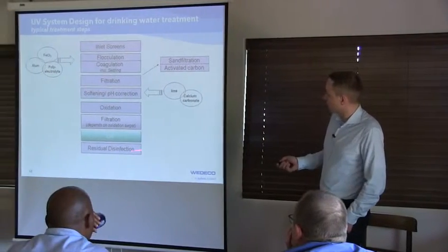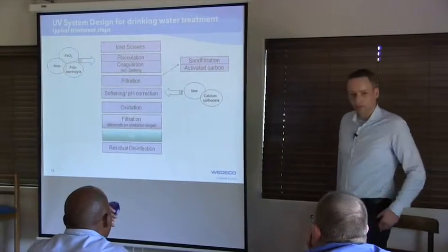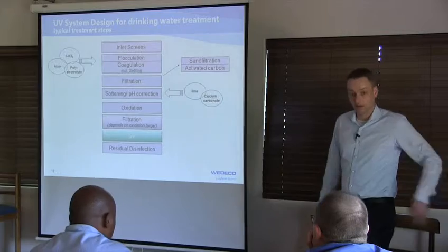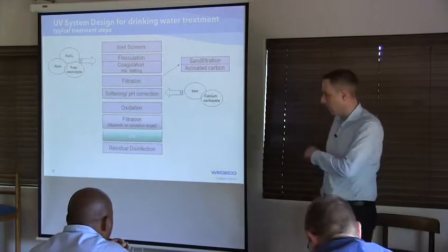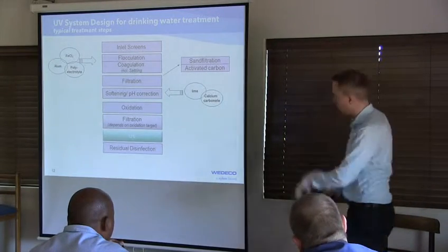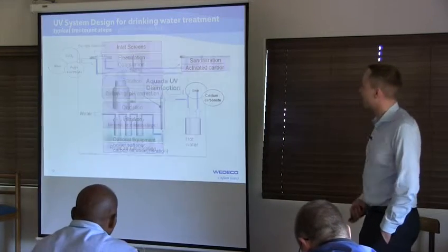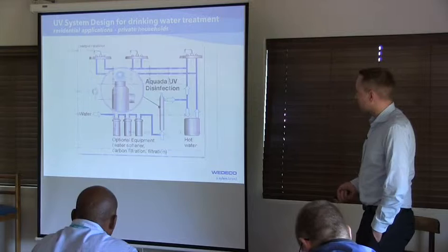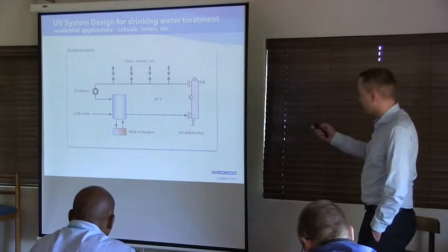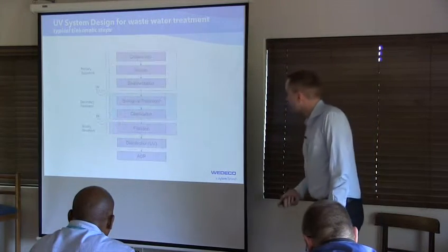But the main short point is you can reduce your chlorine to 1/10 or even less of the normal amount you would look at. And the benefits of doing that will be shown in three more slides. So yeah, we have the same solution for hot water circuits.